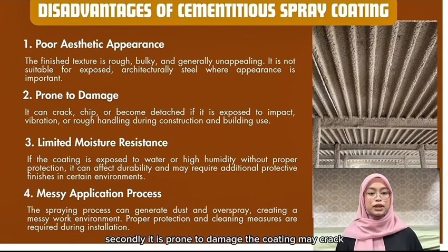Secondly, it is prone to damage. The coating may crack, chip, or detach if subject to impact, vibration, or rough handling during construction or building use. The third disadvantage is limited moisture resistance. If exposed to water or high humidity without proper protection, the coating may lose durability and require additional protective finishes.